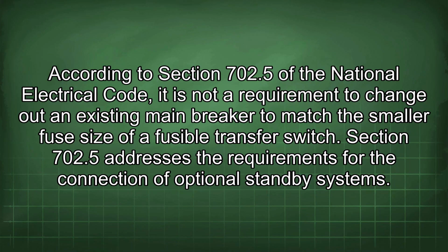According to Section 702.5 of the National Electrical Code, it is not a requirement to change out an existing main breaker to match the smaller fuse size of a fusible transfer switch. Section 702.5 addresses the requirements for the connection of optional standby systems.